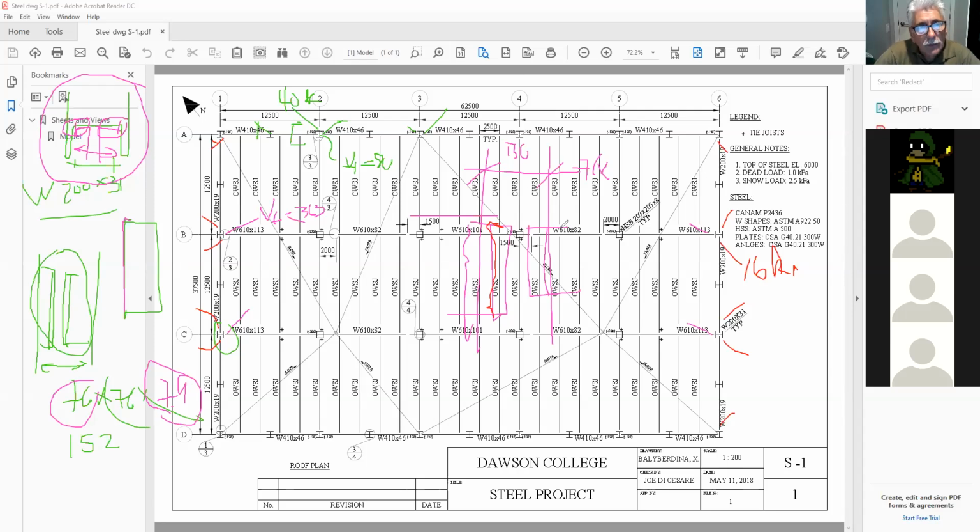You understand? Sir, the VF you gave us from EDA, we don't divide it by 2, right? No. This is the VF value. This is not the load on the beam. This is the actual VF value at that end of the beam. In other words, that's the highest VF value. For these beams here, I took this from load combination number 3, and this one I took from the envelope. This is the highest one that the envelope gave me. Understand? 363 kilonewtons.